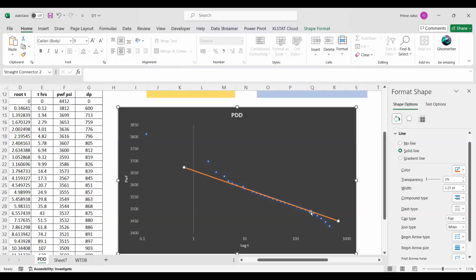But probably this could be the place where the drive mechanisms will start to decline. There are more indications, not just about drive mechanisms. Pseudo steady state flow might have been incurred. Why? Because a reduction in drive mechanism will reduce production. Then the production from the transient period will reach steady, and then it will go to the pseudo steady state flow period. So that might be the effect of it, or else it could be by boundary also.